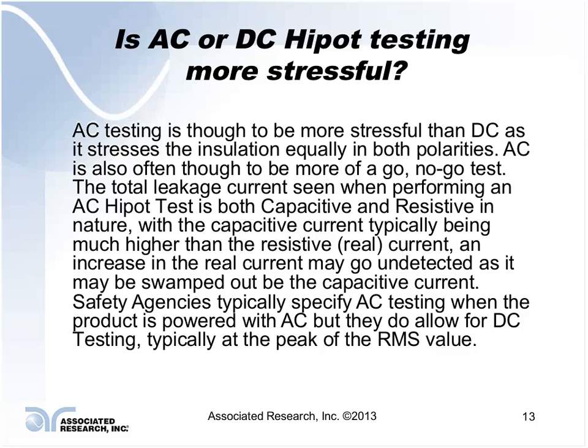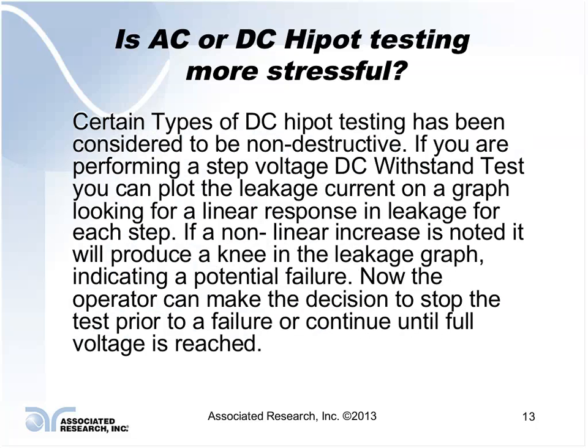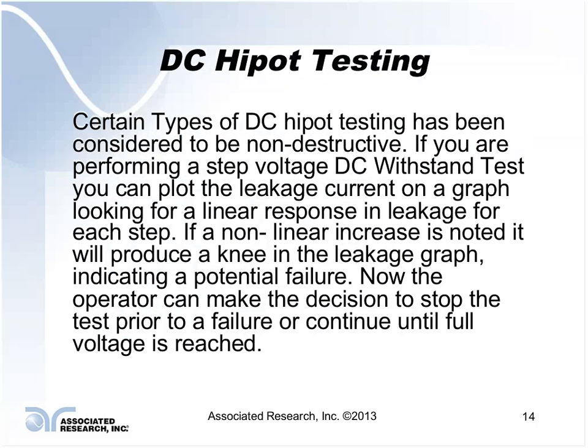You may be doing a step voltage test, where you're charging up the capacitance to a certain level, you're allowing that current to stabilize, and then increasing it again, going up to the next step, charging that product up slowly. One thing to keep in mind in doing DC testing, you are typically testing at the peak value rather than the RMS value whenever you're going through and doing that test. Okay.